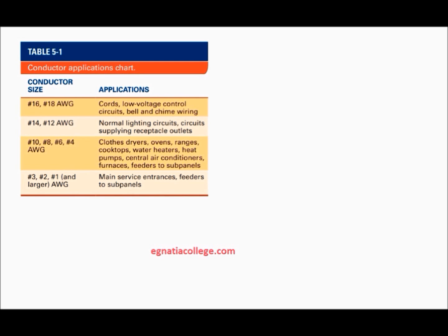The copper wire used in electrical installations is graded for size according to the American Wire Gauge (AWG) standard. The wire diameter in the AWG standard is expressed as a whole number. AWG sizes vary from fine, hair-like wire used in coils and small transformers to very large diameter wire required in industrial wiring to handle heavy loads. The wire may be a single strand, solid conductor, or consist of many strands. Each strand of wire acts as a separate conducting unit. Conductors that are number 8 AWG and larger generally are stranded.